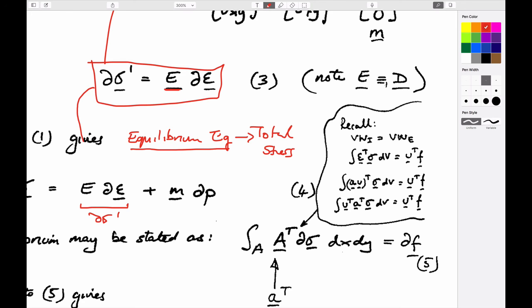The prop I always use is this to be able to describe that. The external virtual work would be the forces that we'd apply that would go through some displacement as you load it. So the external virtual work would be the force that you apply multiplied by the displacement that it goes through. Constant force multiplied by a small virtual displacement. By definition, force times displacement is Newton meters, which is work, and so it's work.